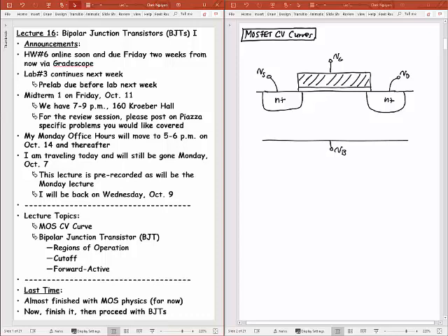When we want to talk about this device, we also talked about the fact that we have a gate polysilicon here, which is conductive. We have an oxide between that polysilicon and the silicon on the other side. The silicon in this case, since it's an NMOS device, is going to be P-type silicon, so this is a P-type silicon substrate. The conductor of the gate, the oxide, and the conductor on the other side, the silicon, make up the capacitor.